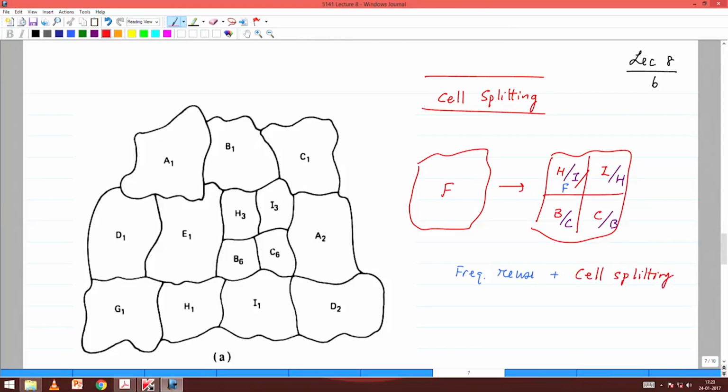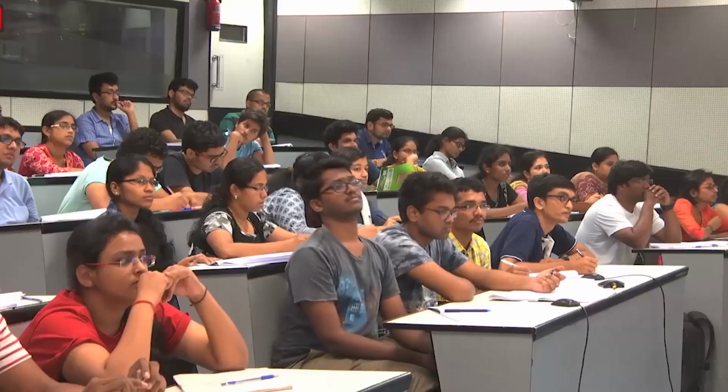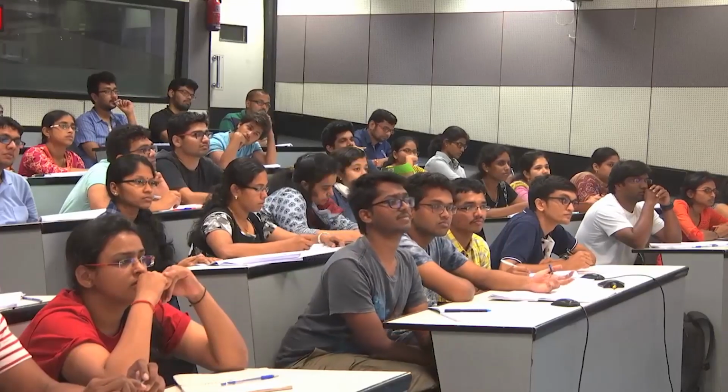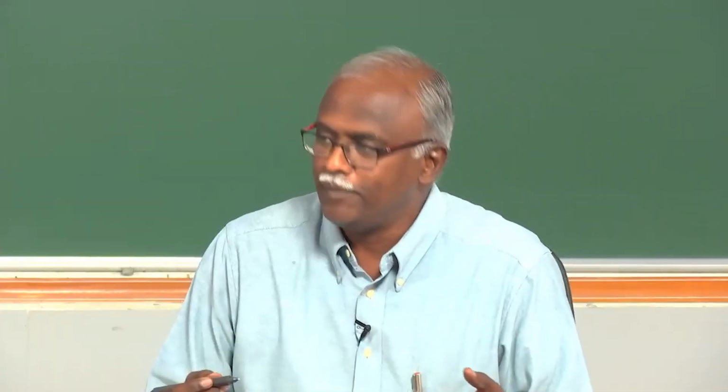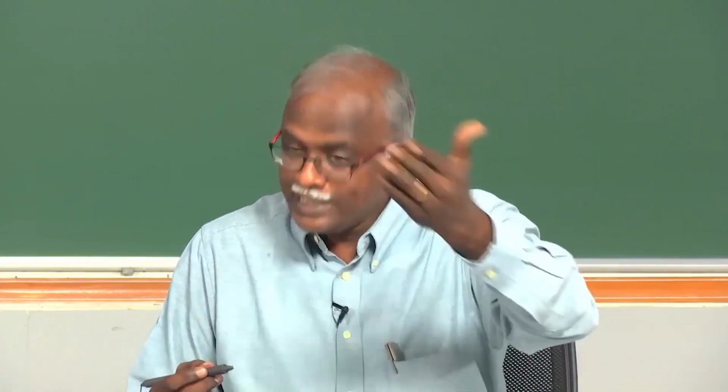So, let me ask you a question. What is the capacity of a cellular system that is designed in this fashion? It's infinity, because I can go on subdividing, right? I can go on dividing into smaller and smaller cells. Where is the price that I pay for that? I'll increase the number of base stations.